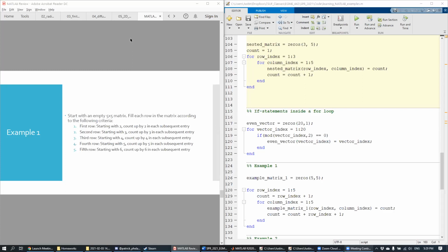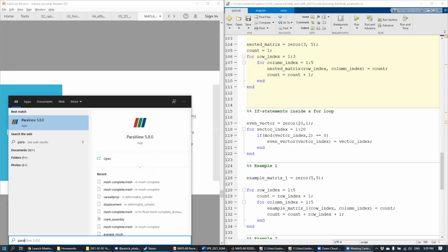I'm not sure if it can do this, but there's an open source software I use called ParaView. I can actually show you the interface here. It's spelled like this. I use this to load STLs, so I know ParaView for sure can read them. Usually I use ParaView to convert between STLs and other file formats that I use for my research. I haven't tried converting to STEP or IGS, but I think it's worth a try because ParaView does have a lot of formats.